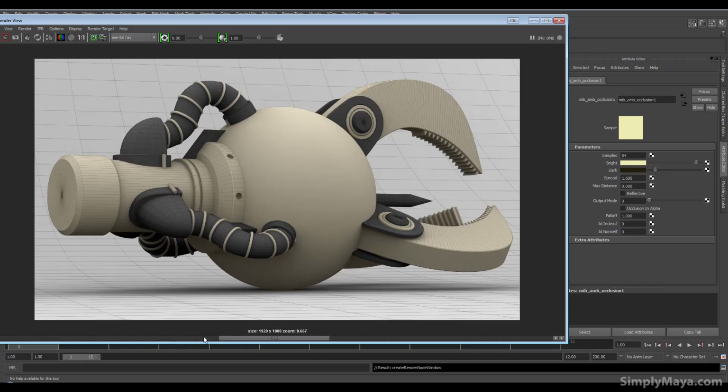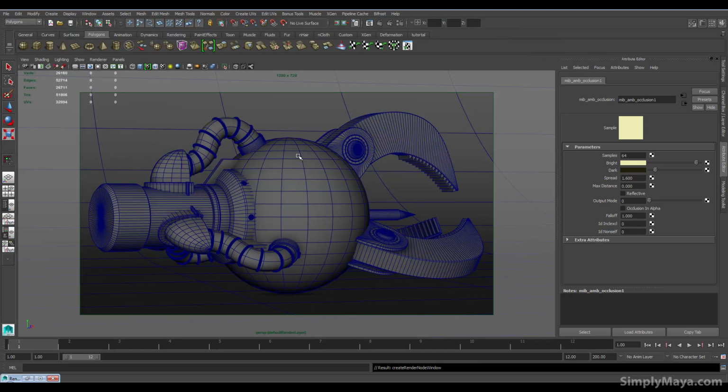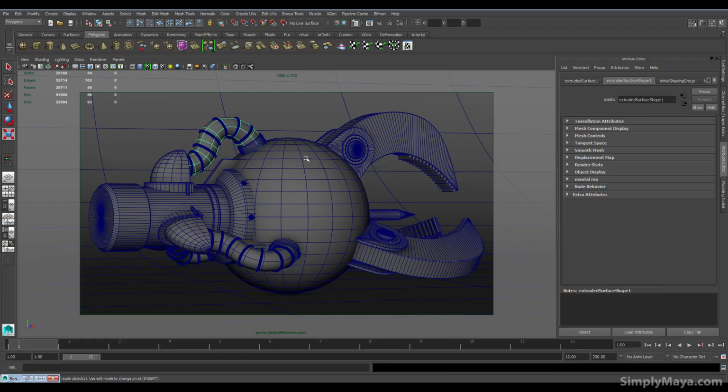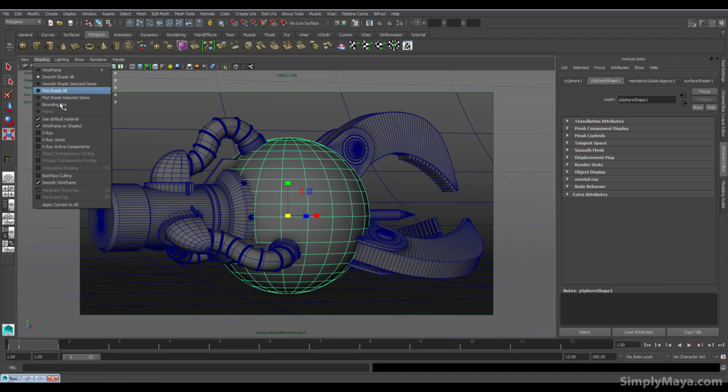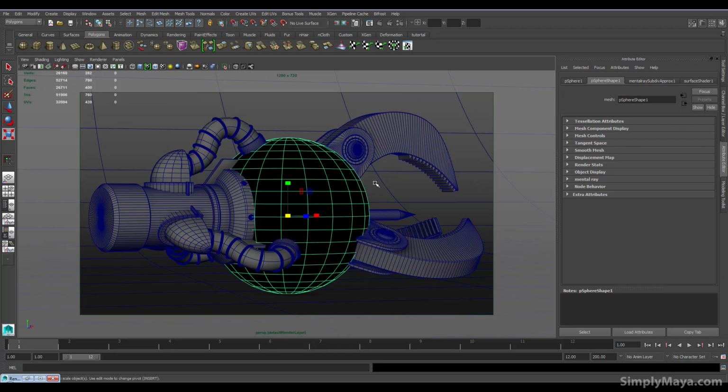Now, what I did when I rendered out was I used two different colors. I wanted to bring in a darker color to accentuate some areas, just to break up the model a bit and make it easier to see what was going on. So for that, we'll need another surface shader, and the reason why you can't see the materials going on is because I have default material armed. A surface shader by default will just appear black. So, once you've got a surface shader on the whole thing, it's going to make this quite tricky to see.